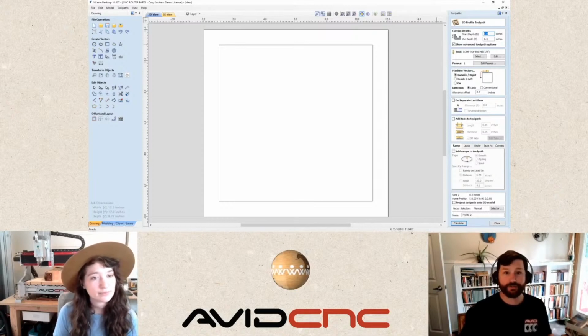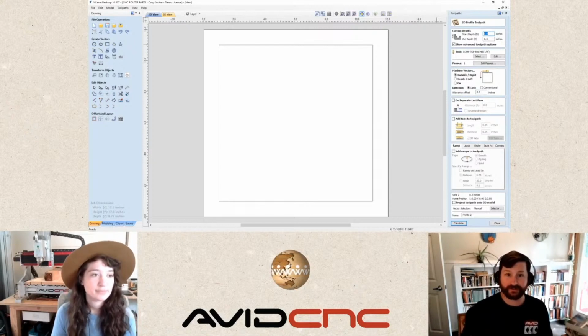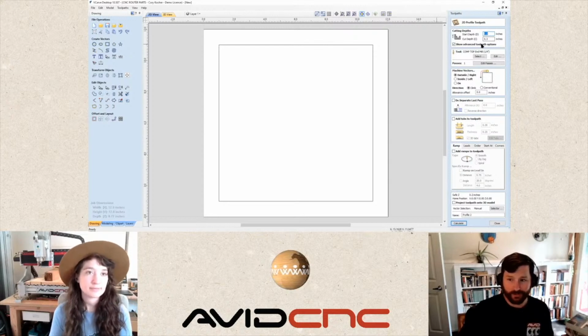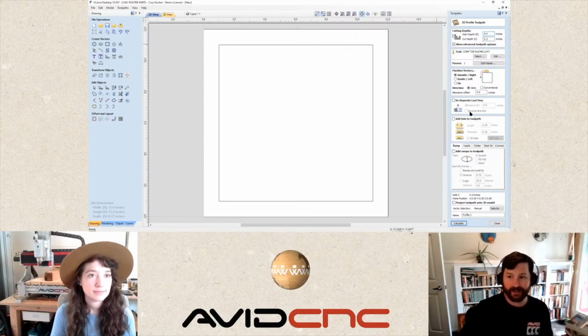Yeah, so I like to do my through cuts actually in two separate toolpaths, and that's because I want my feeds and speeds to be different based on some variables, because we have essentially two different operations that we're going to be completing here. So our first toolpath is just to get that top veneer cut nice and clean and get the down cut part of our flute of our tool into that veneer. And so the ideal depth for that with our 1/4 inch end mill is 0.3 inches deep. So that's what I currently have set here for the cut depth.